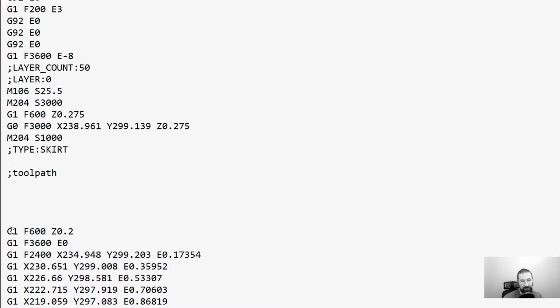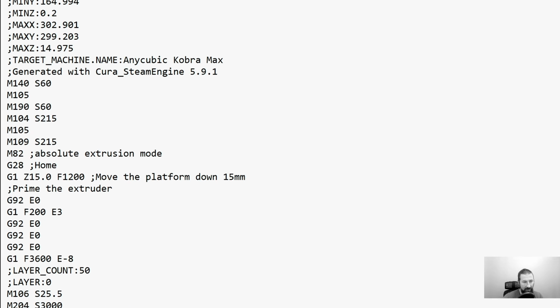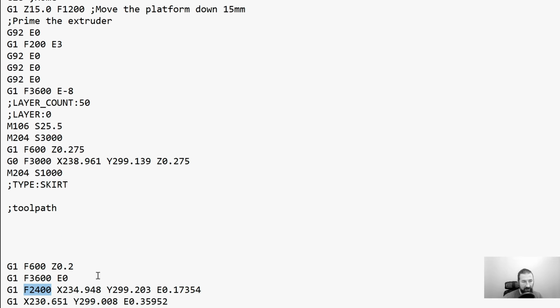If you see, these G1 commands are extruded movement commands. Extrusion is a special case for 3D printers. In normal CNC, you do not have this extrusion command, and instead it just moves your milling bit, for example. Besides G1, you also have the G0 command, which is a normal travel move. In 3D printing, it means travel or move without extrusion. Different feed rates are basically different speeds. You can set the speed here, and it stays that way as long as you are not changing it later in a following line.